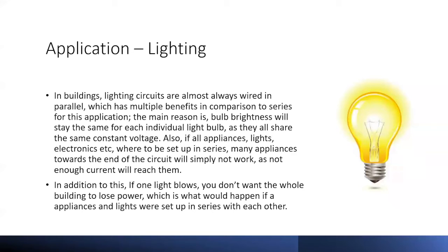Application: lighting. In buildings, lighting circuits are almost always wired in parallel, which has multiple benefits in comparison to series for this application. The main reason is bulb brightness will stay the same for each individual light bulb, as they all share the same constant voltage.